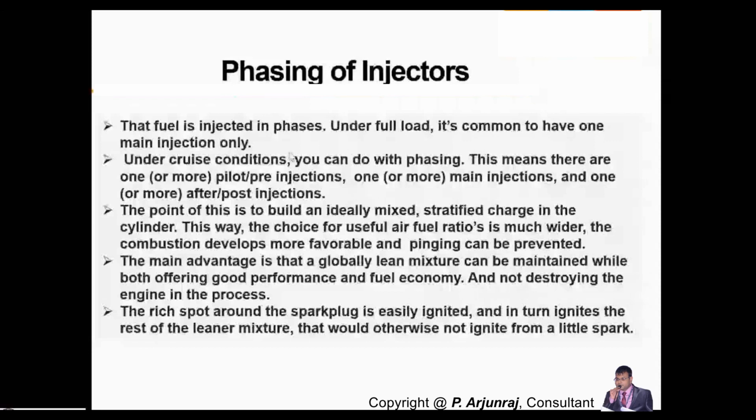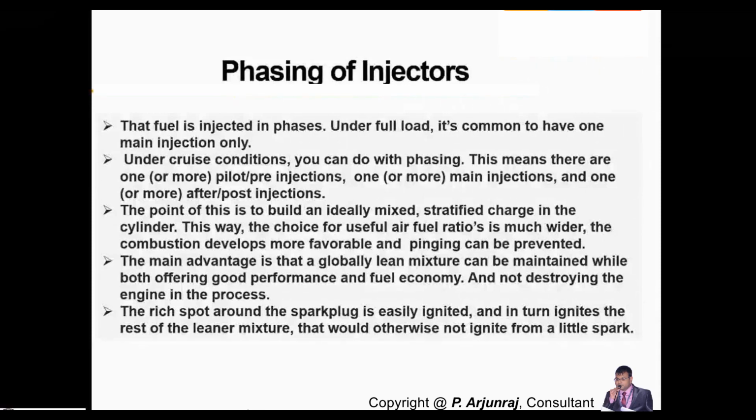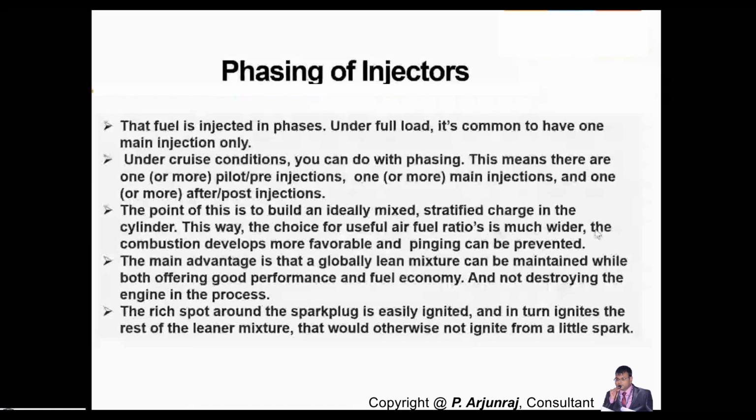By phasing the injector, adjusting the quantity and the period of the injections, this will help for maintaining the lean, rich or stoichiometric mixture, and that will help for maintaining the emissions as well as the performance of the engine. The choice for going for useful air flow is much wider with phasing, and the compression you get will be more favorable, which helps avoid incomplete combustion.